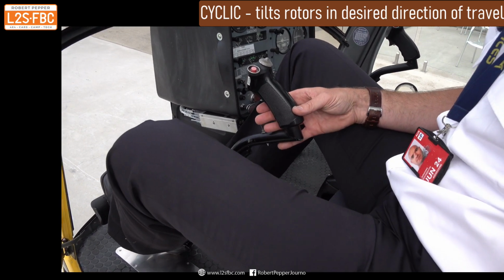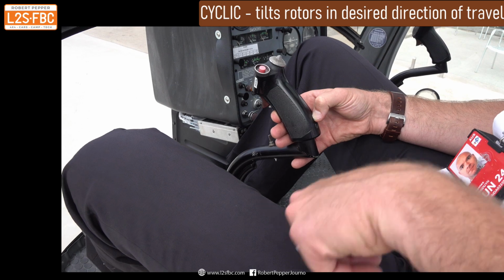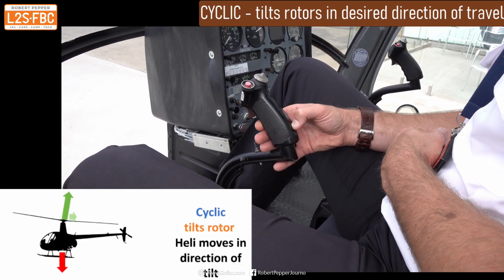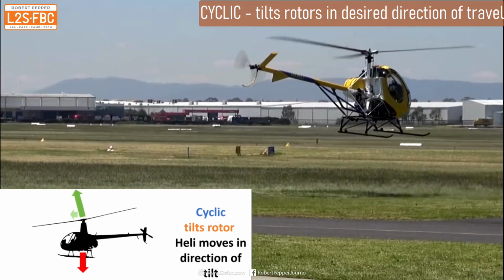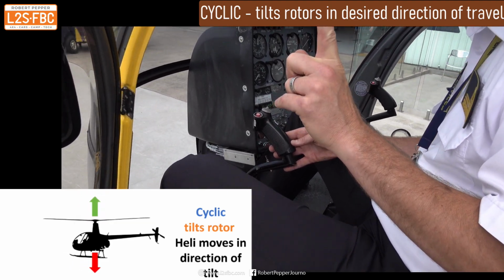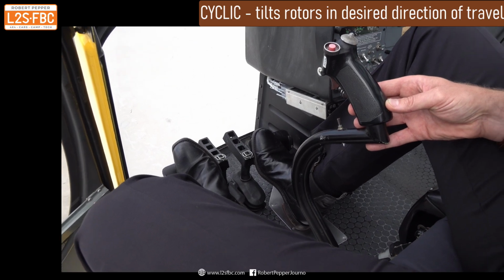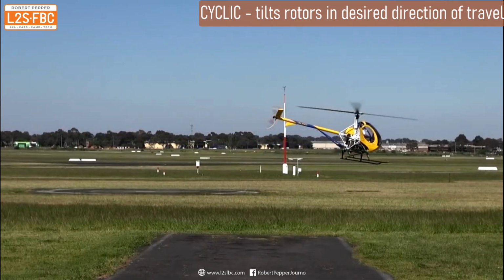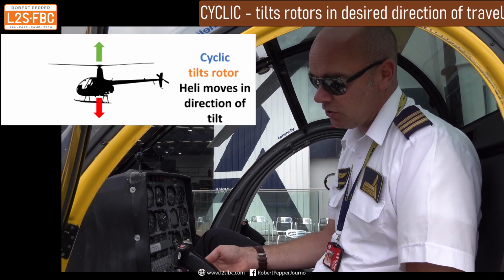So the one that most students struggle with in the beginning is the cyclic, held in the right hand, different shapes, but the cyclic is the device with which the pilot controls the main rotor. You push the cyclic forwards, the entire disc tilts forwards. As such, your total thrust tilts forward, and the machine will start to fly forwards. If you were in a hover, or if you were already in forward flight, you will actually increase your airspeed.